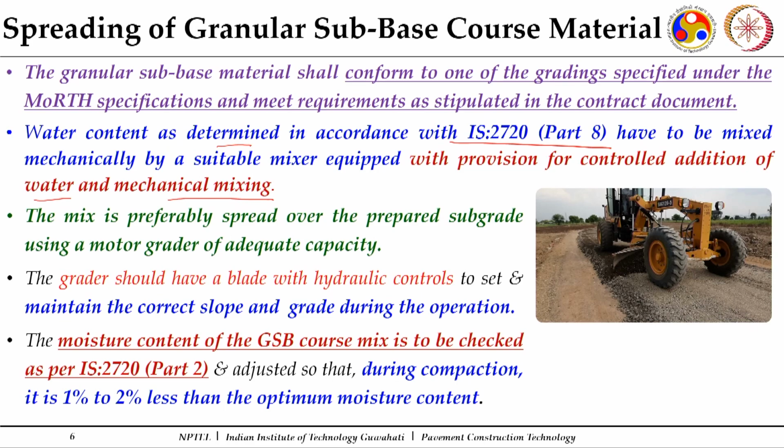And once mixed with water, it should be spread over the prepared subgrade. Here a grader plays a fantastic role, and it should have adequate capacity. Capacity means the width it can spread, depending upon the hydraulic blade which is there. You can go for wider widths. So, the grader should have a blade with hydraulic controls to set and maintain the cross slope and grade during